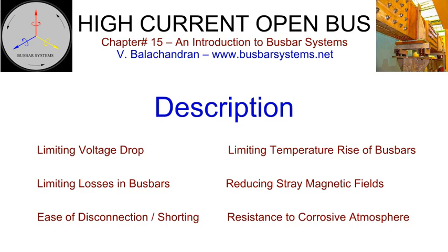With the cost of energy ever creeping up, the efficiency of a plant is defined in terms of usage of kilowatt-hours per ton of metal produced. With aluminium having 60% of the conductivity and 35% of the cost of copper by weight, industries are forced to rethink ways to save energy and capital cost. It is not uncommon to see high current DC connections having a combination of aluminium and copper bus bars in different sections of the plant.